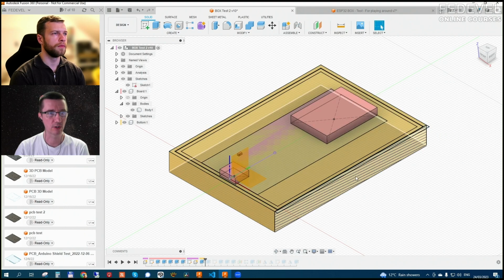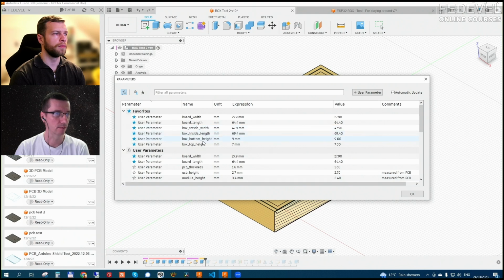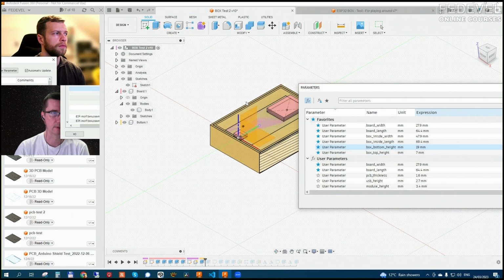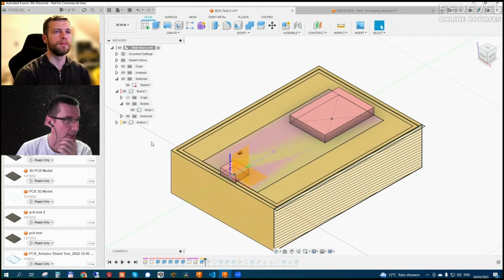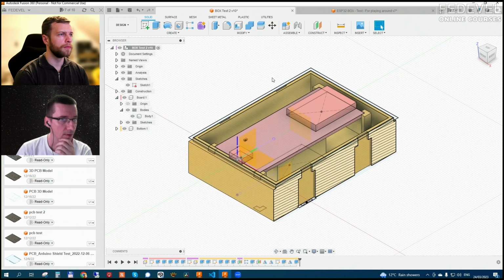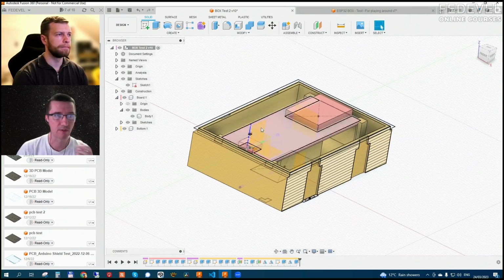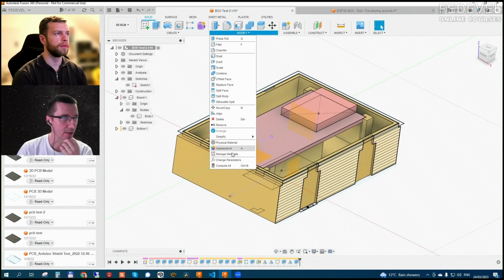So if I would like to change the height of this, I can simply go to parameters and bottom box height. I change it, let's say, to 19. Yeah, and it's now deeper. And everything should be still okay. If I move it, see, everything is still referenced correctly. I did it this way because if there are pins or something, you can make it deeper and then you can have there also the pins and connectors with it. I'm going to put it back so I don't forget.